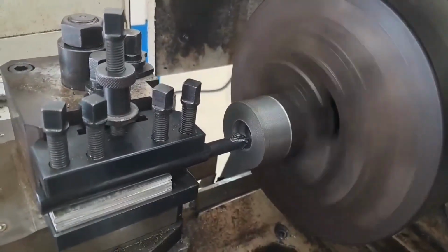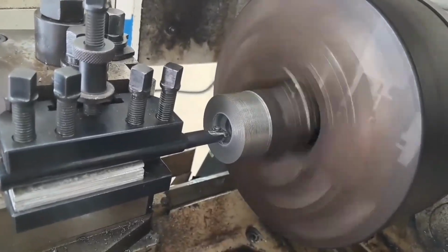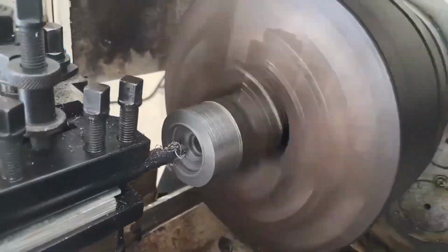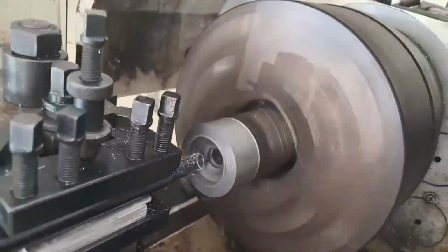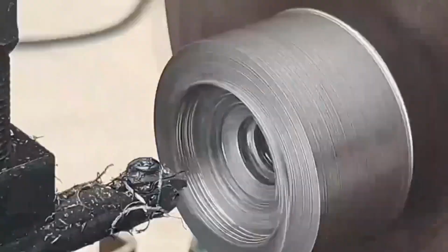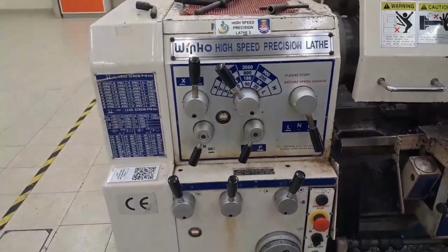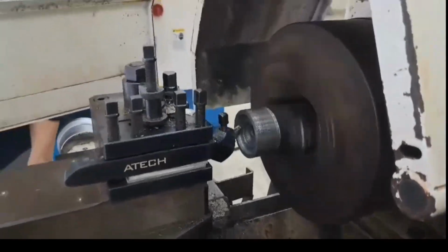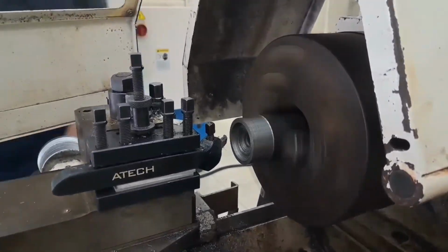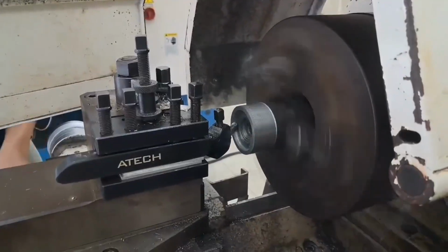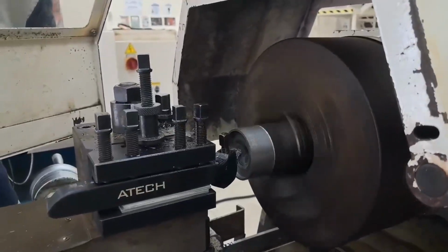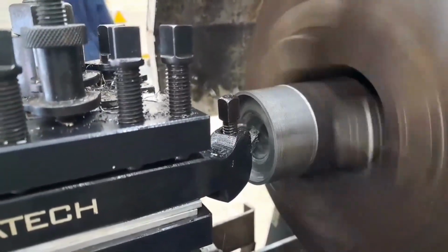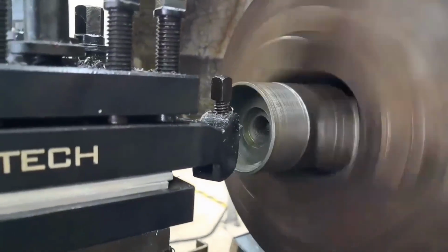After the drilling process, to create a small hole for the boring, the process of boring is executed. The cutting tool for boring is mounted on the boring bar to reach the full length of the bore. The process of boring is executed to make the hole in the workpiece bigger by increments of 1 mm. The process of boring is also to make a good finish for the surface inside the workpiece.